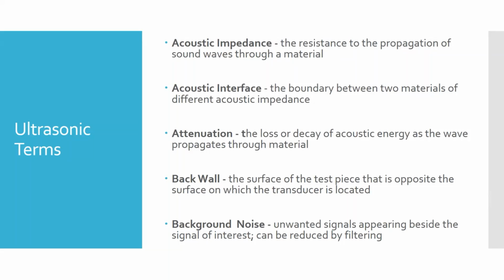In fact, this big transducer I have in my hand is designed for doing composite inspections, where you have a lot of that interference. Versus when we're doing aluminum parts, the transducer you're going to use is going to be about this size, because there's a solid chunk of aluminum. It doesn't have all those different interfaces. It's homogeneous, versus composites that are not homogeneous.